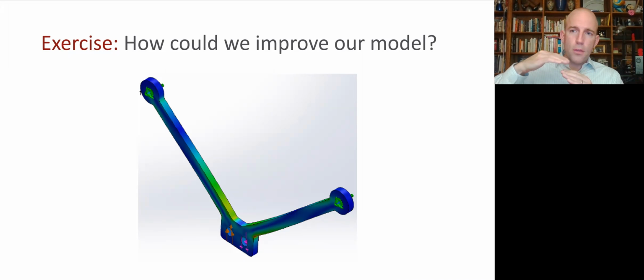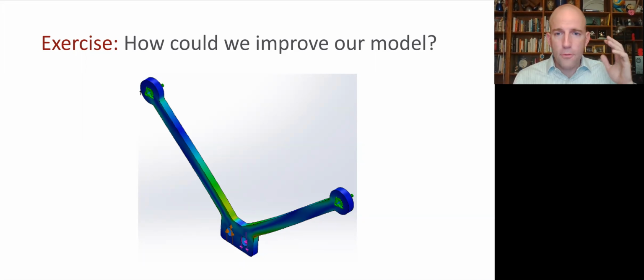And as we move through the center of the part, the stress goes to almost 0. And then when we continue on to the other edge, the stress gets high again. So very high stress, then almost none, and then very high again on the other side. That's the pattern of stress that we learned about in our solid mechanics course that occurs when you have bending. So the finite element analysis was also trying to tell us that this was an issue.